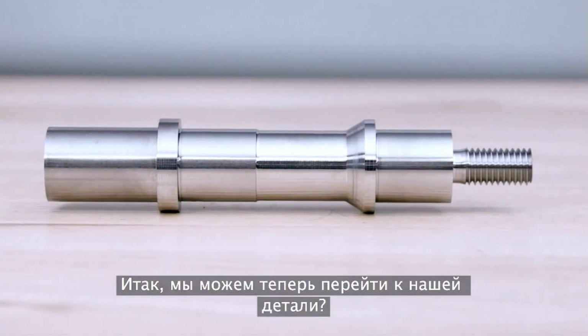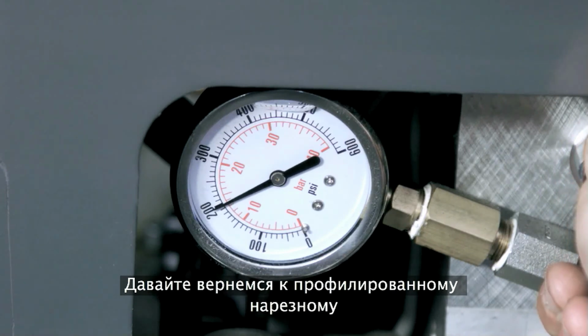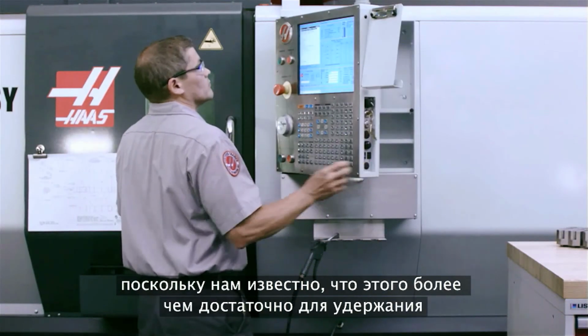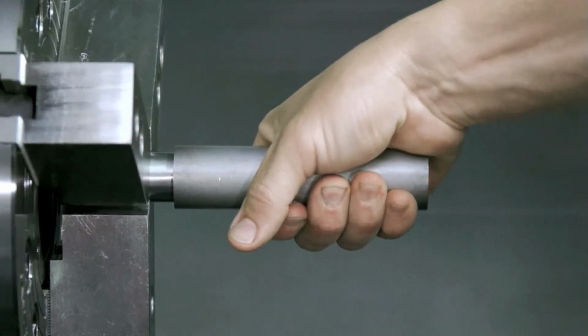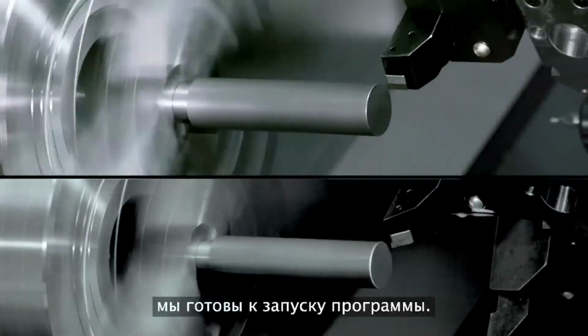Okay, can we make our part now? You bet. Let's return to the profiled and threaded shaft we looked at the beginning of the video. We'll use a tailstock pressure of 200 psi, since we know this is more than sufficient to keep our part in place without any unnecessary amount of force on our part and machine. With all the aspects of our tailstock support accounted for, we're ready to run our program.